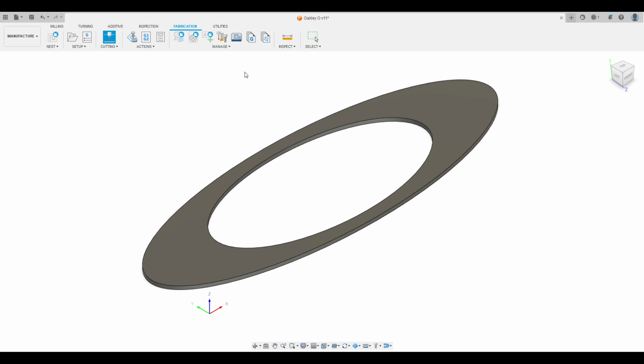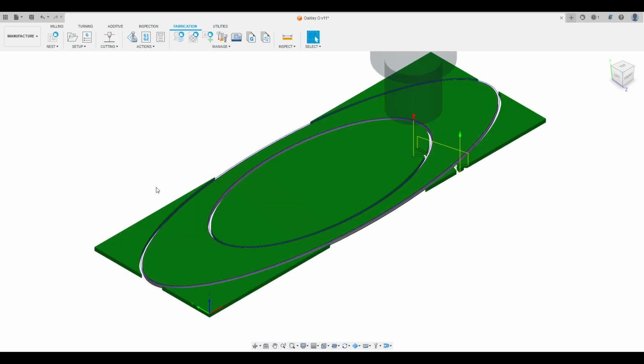Now you guys won't see this. What you will need to do is come over to your cutting tools in the inches. Yours will look like this when you first click on it, so I'm using metric as an example. It said library turned off. You just need to select turn library on, and you'll be able to see all these cutting tools above. In this case, we're going to be using the plasma cutter. I'm going to go ahead and select that and hit select or double click it, and then we could hit OK. This is going to create our toolpath.